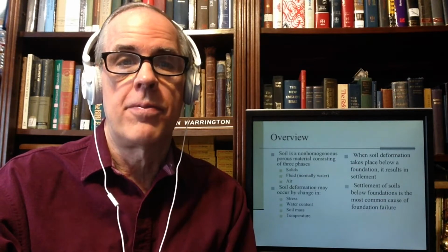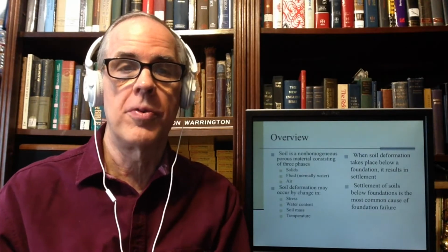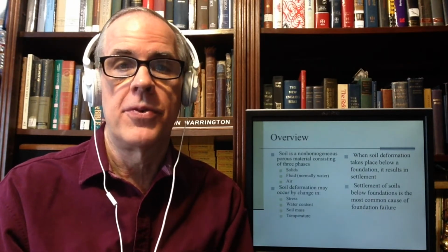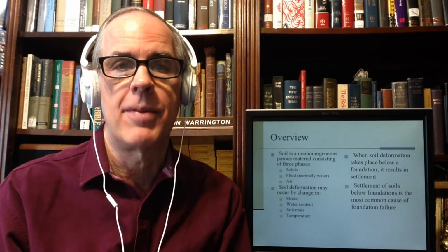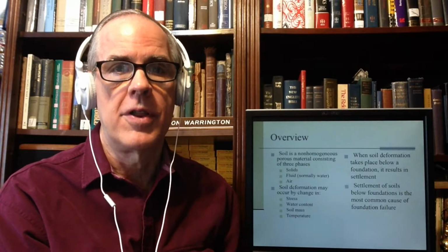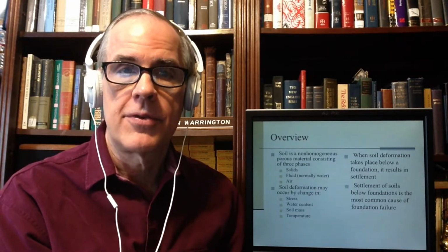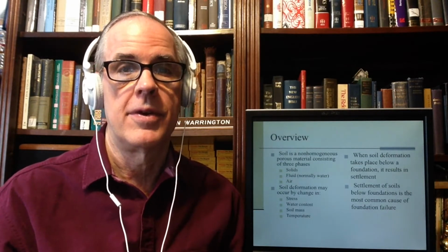If you have put a foundation on the soil and the soil deforms below you, it is referred to as settlement. And as I've said before, settlement of soils below foundations is the most common cause of foundation failures. We're going to look at examples in this course of foundations with catastrophic types of failures, but settlement failure is by far the more common. It may not be as catastrophic, it may not be as spectacular, but it can be very expensive.